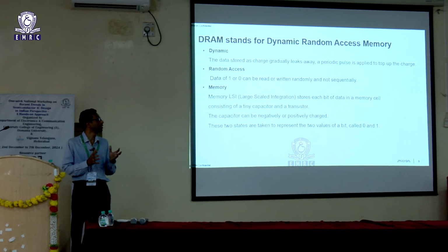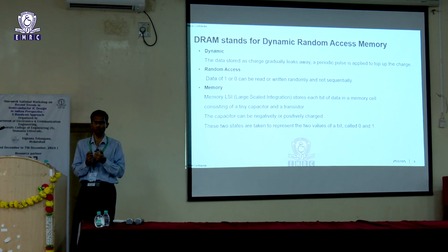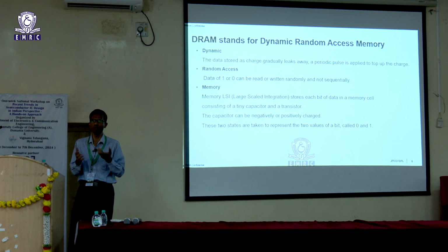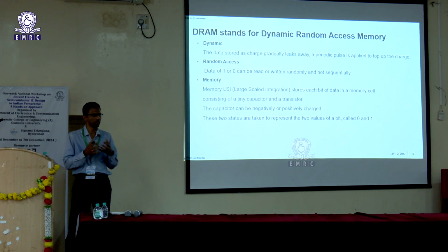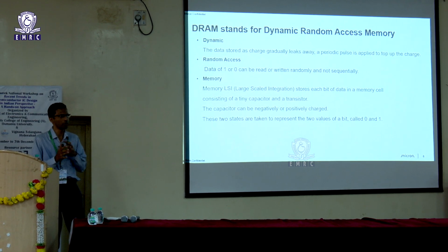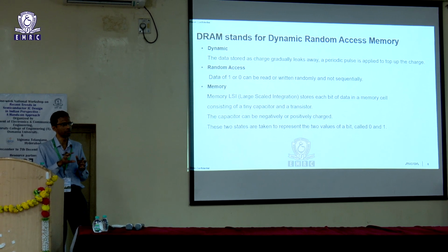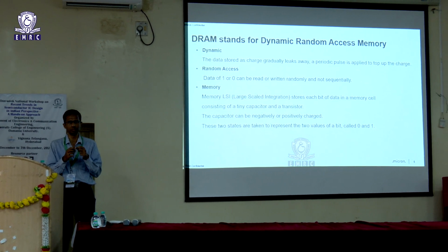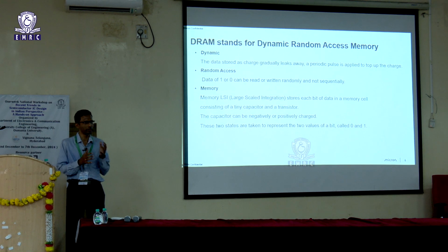And it's dynamic because the data is stored on a capacitor, and you will have to refresh it periodically because charge gets lost over time. You will have to have a periodic refresh somehow built into the system. That's why it's dynamic in nature, as opposed to static RAM, wherein you have a cross-coupled inverter structure, which will hold data indefinitely as long as you have it powered up.